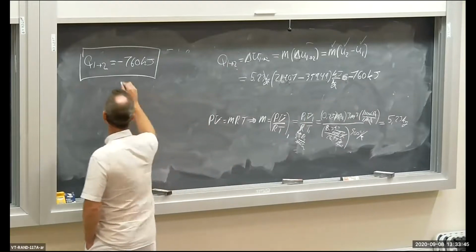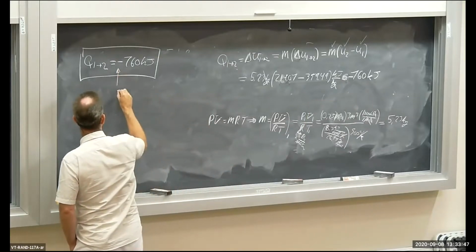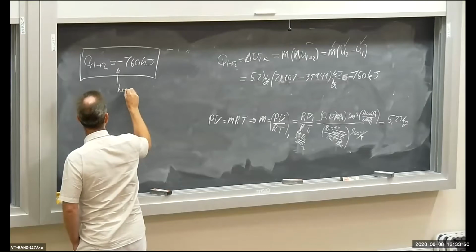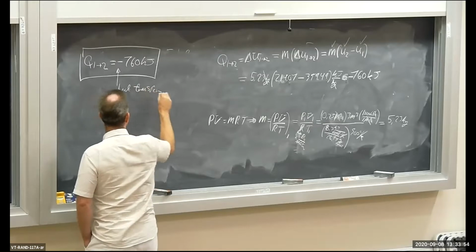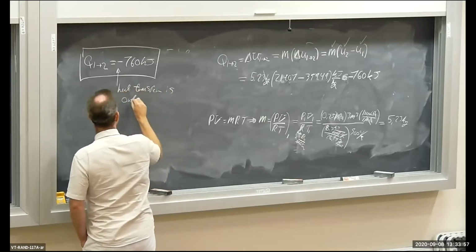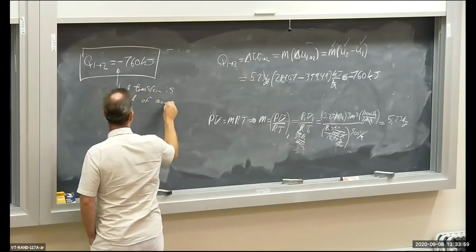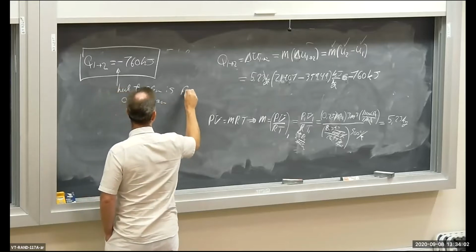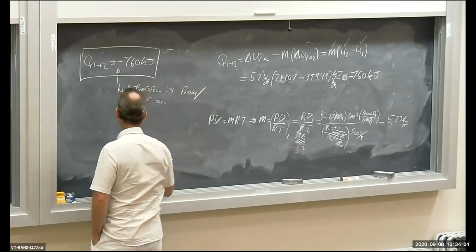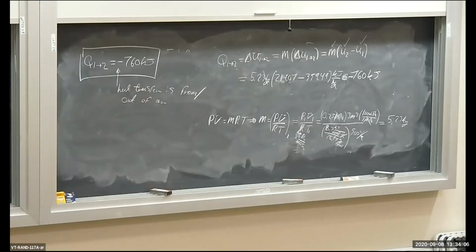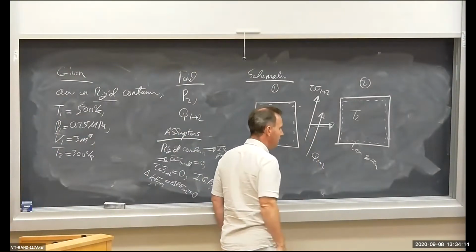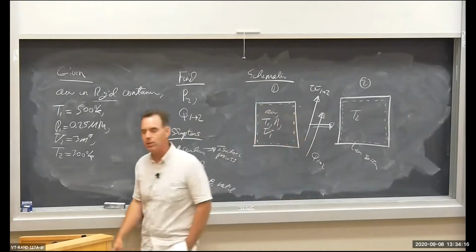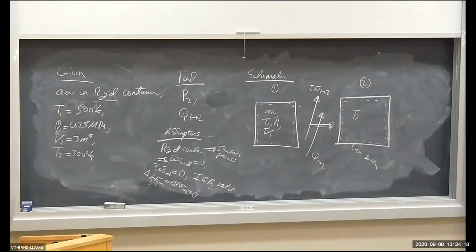Why the negative sign? Heat transfer is out of air. Heat is being extracted from the air. We defined heat transfer as being in positive, so we got a negative sign, and what that means is heat is being transferred out of the system.